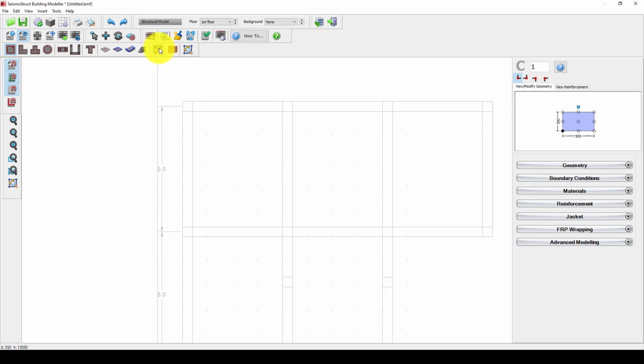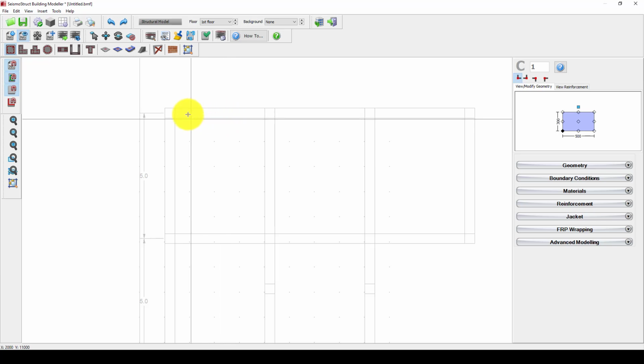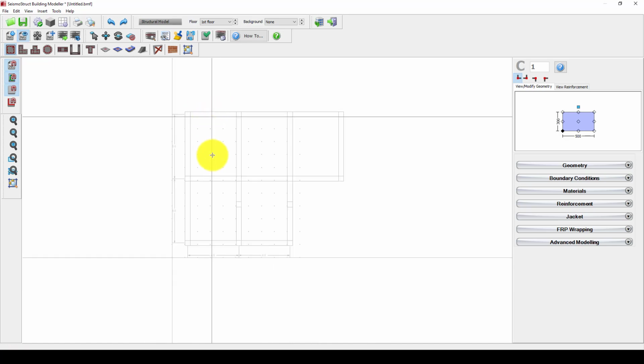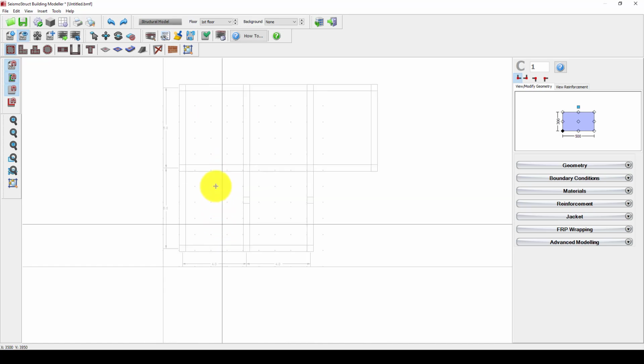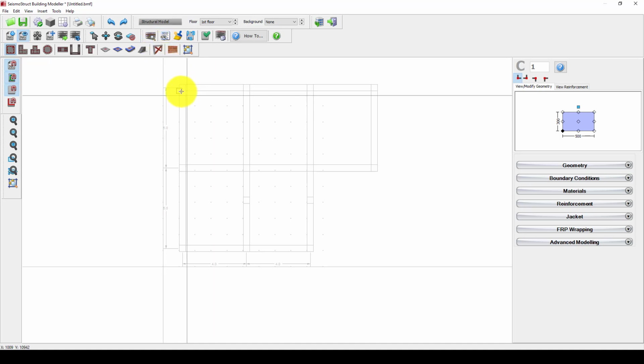Just that this bracing can take the lateral force, but when the lateral force transfers to the beam column, the beam column will be damaged. So it's a little technical, and you can retrofit, including adding jacketing for the columns and also adding the bracing. Now you can suppose this structure is already existing. If I consider the same existing column and add bracing, then you can change the methods. But the main purpose of this tutorial is how you can evaluate your work using an existing time history record.